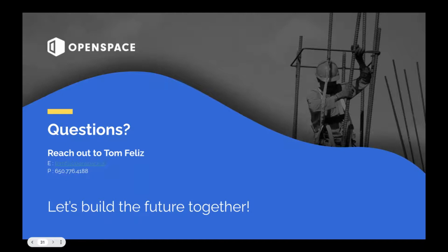Yeah, PPC is plan percent complete. It's basically the metric of what got completed that week and what didn't get completed. It's a task that you do during the weekly work plan, and then it measures out. Having 100% PPC is not necessarily a good thing, because that means you're probably not pushing your crews enough. But having low PPC means low reliability of promises, which then creates a lot of variability in the schedule. So having a high, accurate PPC is really good for jobs because that's what creates flow on the project.